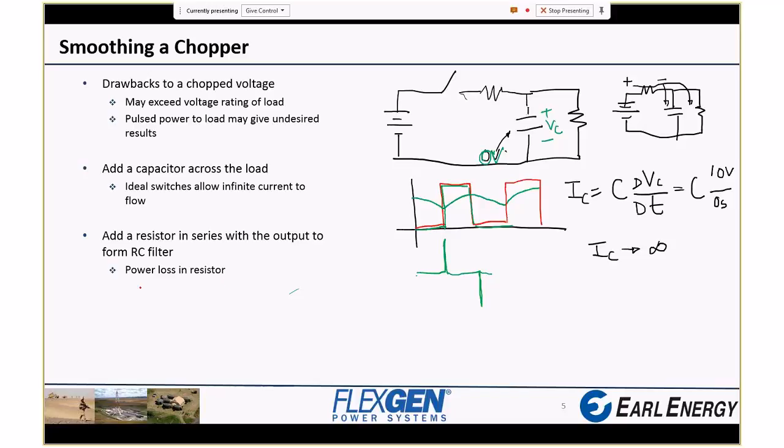But the drawback is kind of the same as in the resistor divider circuit we did on the last slide. However much current is demanded by this load has to flow through this resistor on average. So you still end up with a power loss in this resistor, given as the square of the load current times RS, the resistor.